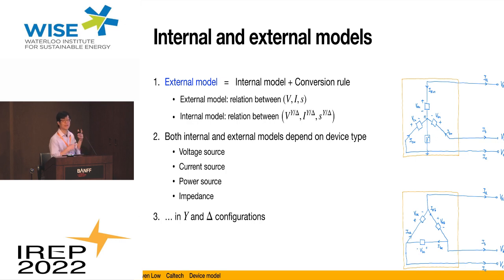sequence terminal voltage. Now, typically, depending on the application, we're given sufficient information. Let's say there's a reference voltage in the network, for example. Then that will allow us to figure out what gamma is. But we cannot just assume it's zero. It may not be in your application. And therefore, you will get the wrong solution if we don't keep track of it. In the absence of additional information outside this model, there is an arbitrary constant. Similarly, given I, there's an internal current vector, which is given by this, and beta is this arbitrary constant, which is the zero sequence internal current of the delta.